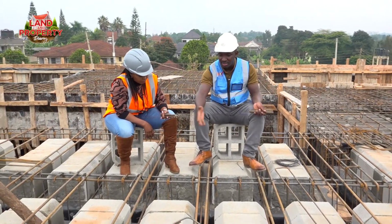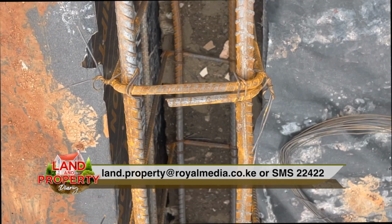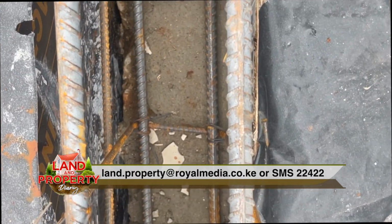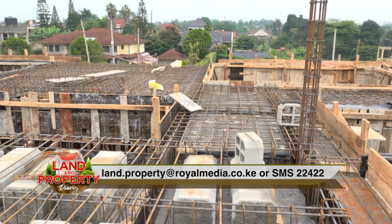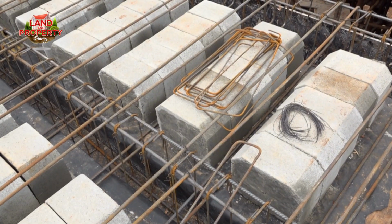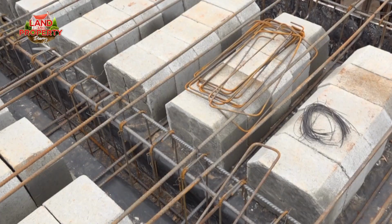Okay. At this side, we are using hollow pot slab because the client wanted a bit of warmth in the house. And hollow blocks really help in that. For the slab, here we have ribs. These ribs are going to take the load from the slab all the way to the beam, and the beam will take the load to the columns. To the columns now? Yes. Okay. They are placed differently.